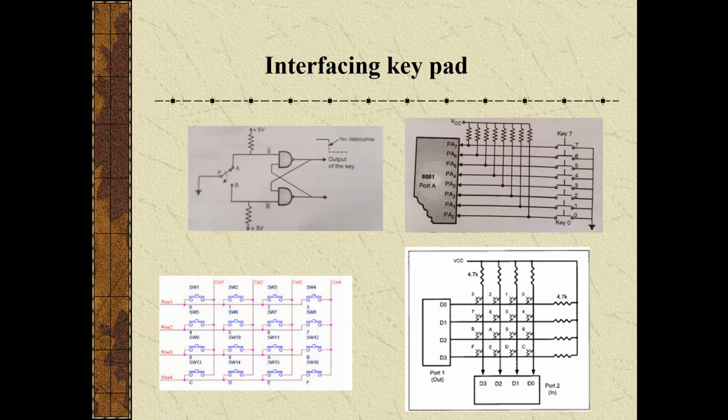We have seen the program for this debouncing. In our program, we are considering software debouncing. What is software debouncing? It is a technique in which the microcontroller waits for a minimum of 20 milliseconds before accepting a key as an input. After 20 milliseconds, the pressed key is accepted by the microcontroller. This process is called software debouncing. We call a delay in our program to overcome this debouncing problem, so we are accepting software key debouncing.